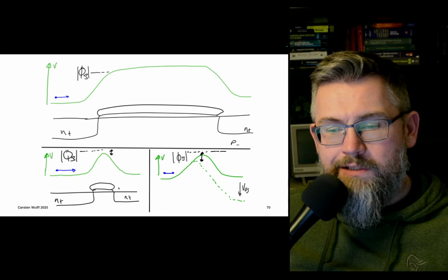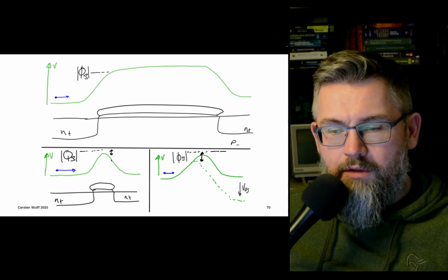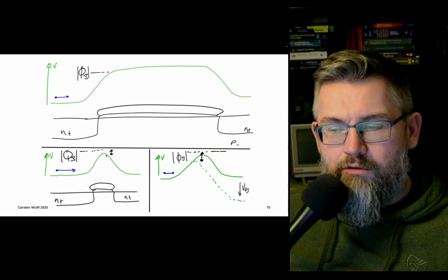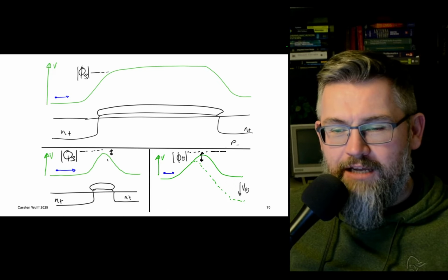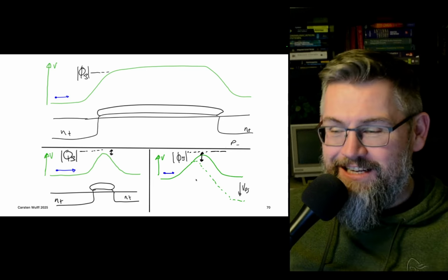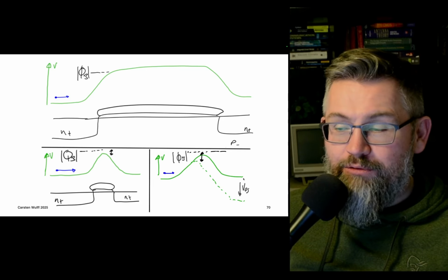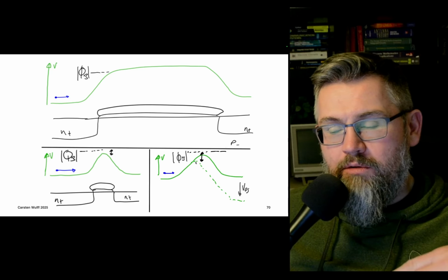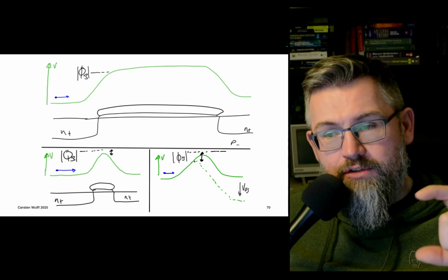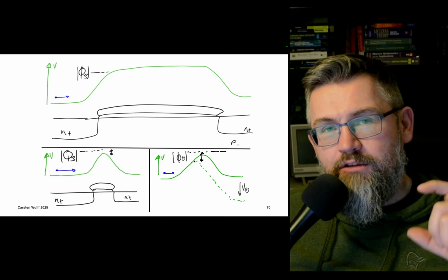So if we make the transistor really, really small, then the energy barrier on the top here doesn't necessarily go that high. There's a bending. And what can happen is, as we increase the VDS, which is reducing the energy, we can pull down the energy barrier at the source side. And this is called drain-induced barrier lowering.